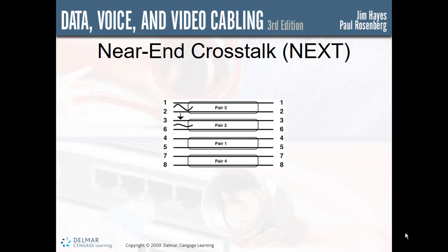The pair carrying a signal is the transmitter, and every other pair becomes a receiver. The cable construction, including the variation in twist rates in the pairs, is designed to minimize this phenomenon called crosstalk. Like everything else, crosstalk is frequency dependent, so it must be tested over the full frequency range specified for the category of cable being installed.